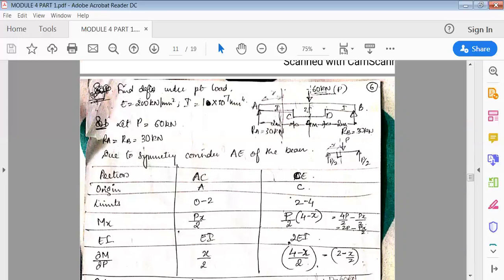now here what I've done is instead of 60, I'll put this 60 as P. So if P load is acting downward, to stop that, there is P by 2 acting upward on either side. So I have shown it here. P is acting down. To stop that, P by 2, left side, right side. And the reason I'm substituting this value P is because according to Castigliano's theorem, the reactions and all should be with respect to P, so that we can differentiate it later.